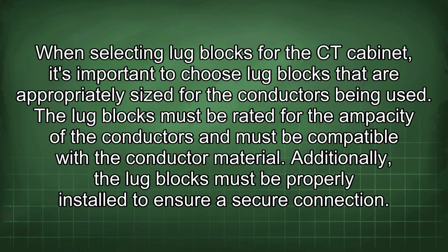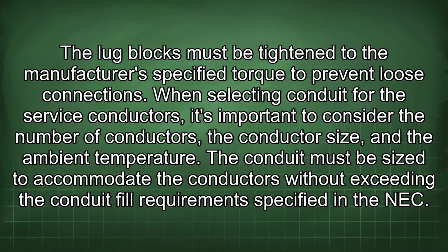When selecting lug blocks for the CT cabinet, it's important to choose lug blocks that are appropriately sized for the conductors being used. The lug blocks must be rated for the ampacity of the conductors and must be compatible with the conductor material. Additionally, the lug blocks must be properly installed to ensure a secure connection. The lug blocks must be tightened to the manufacturer's specified torque to prevent loose connections.